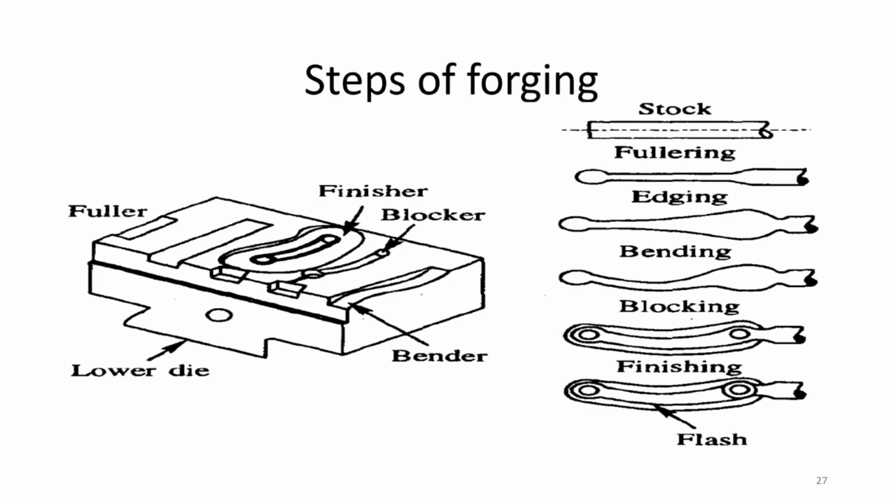For the liquid shrinkage, no, you don't need to consider it, because if there will be shrinkage in your casting, then it won't be of any use. That can't be compensated with the pattern allowance. Pattern allowance is for the draft allowance and all this solid shrinkage part. Okay.